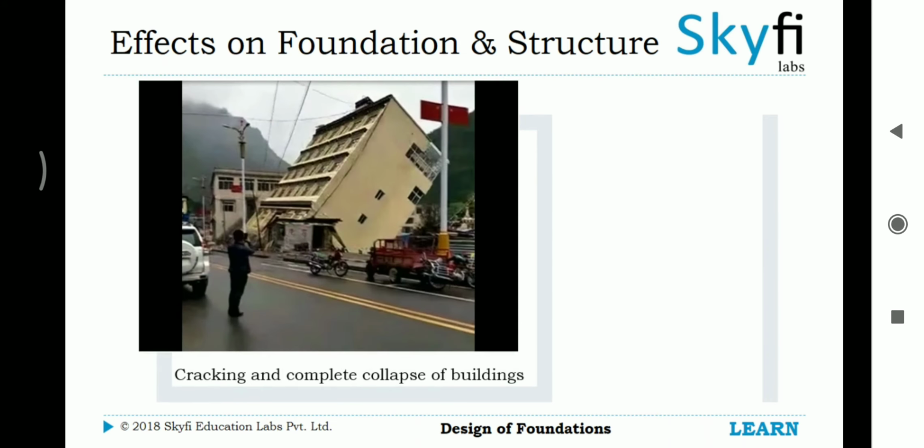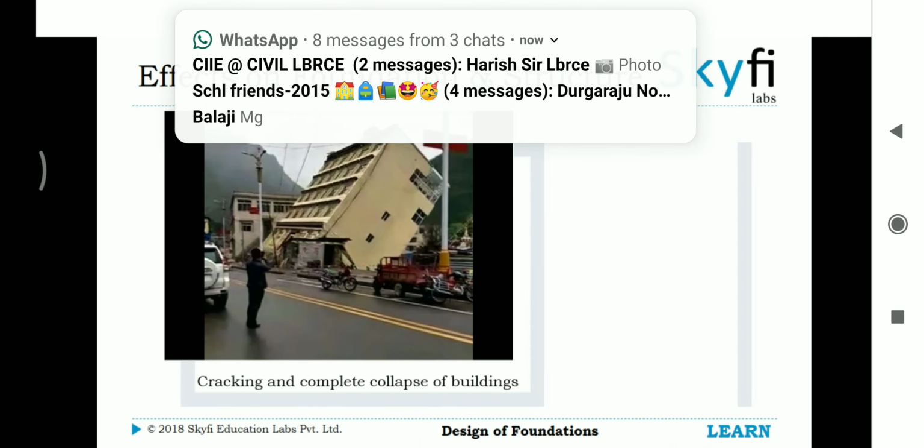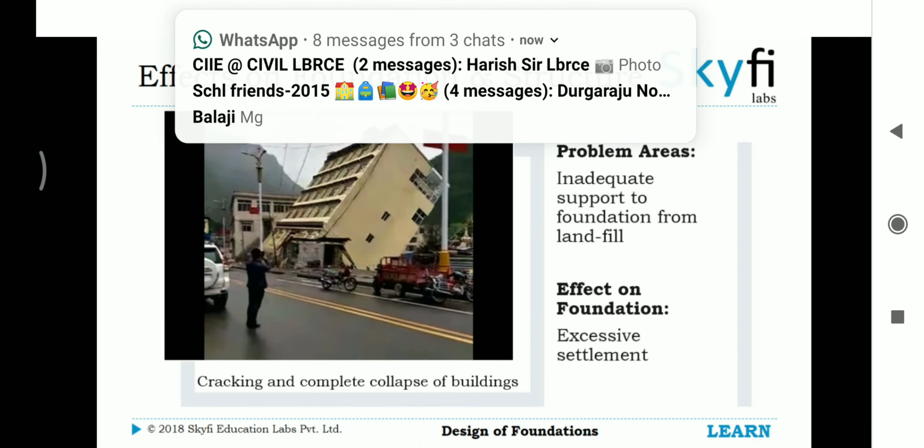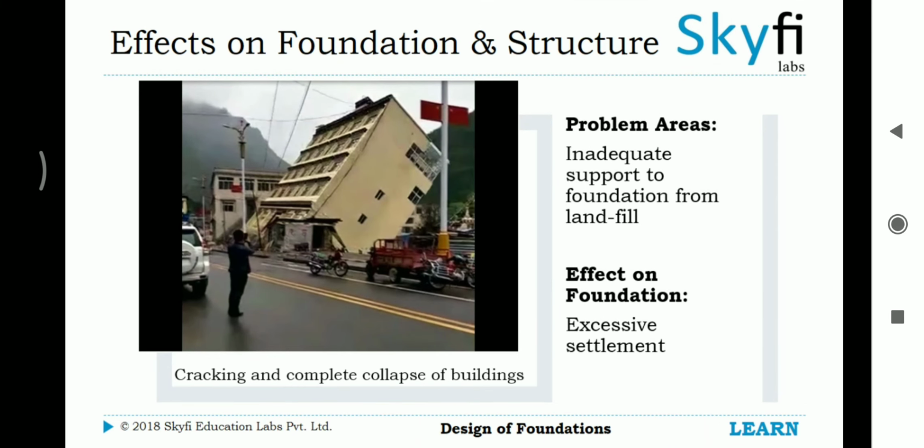In some cases, the cracking of the structural elements is so severe that it leads to collapse of the building itself. This happens when the support to the foundation from landfill is inadequate. Consequently, this leads to excessive settlement of the structure.